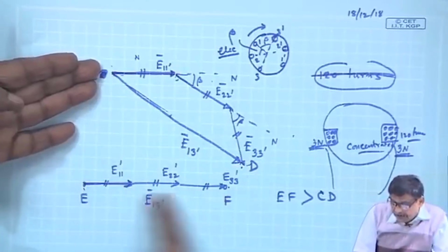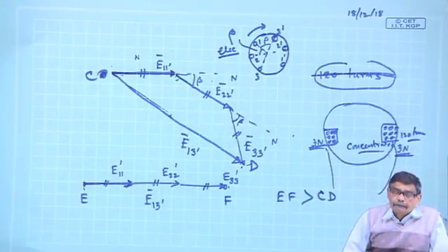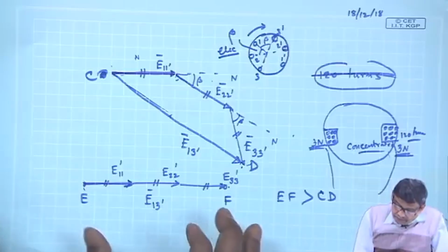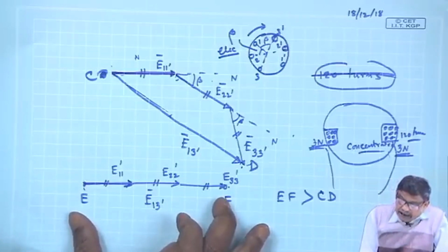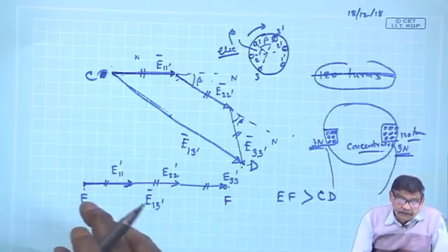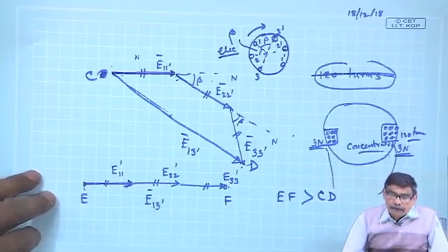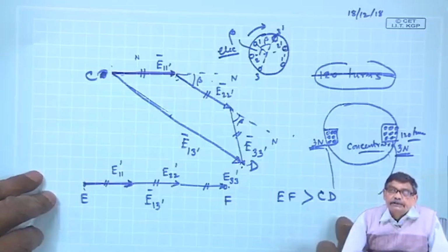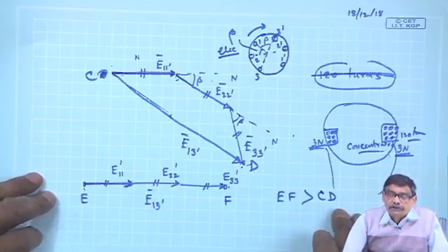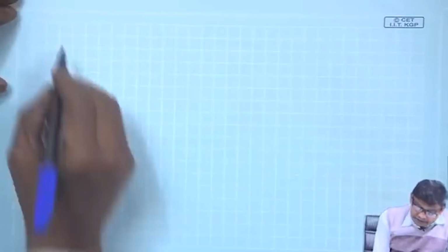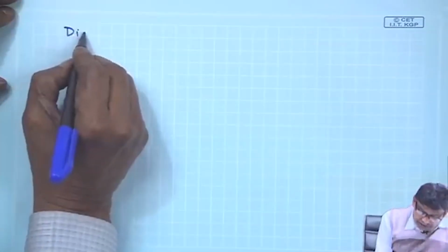Here it is as if you are adding these 3 voltages algebraically. So, I must now compare the resultant voltage available across the combination of the 3 coils connected in series when they are concentrated and when they are distributed, what is their ratio. So, the problem statement is, and in fact, this is called distribution factor.